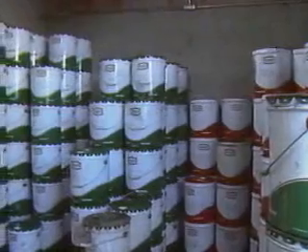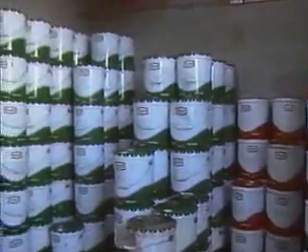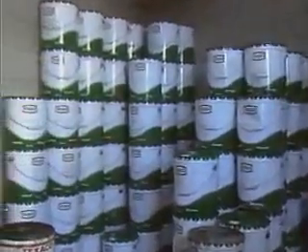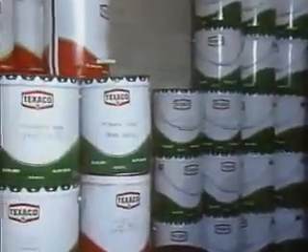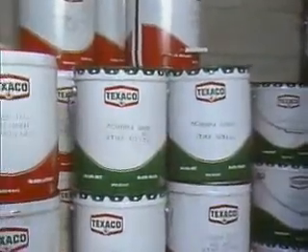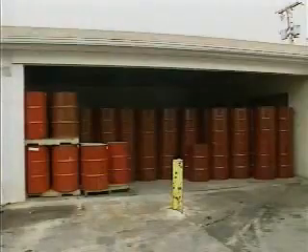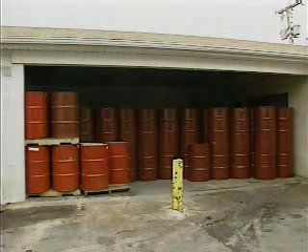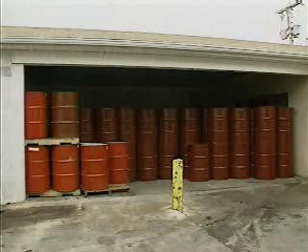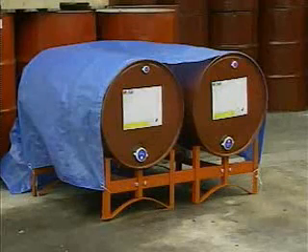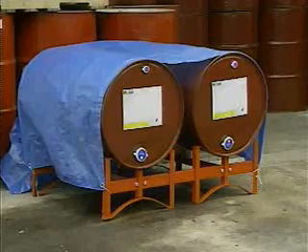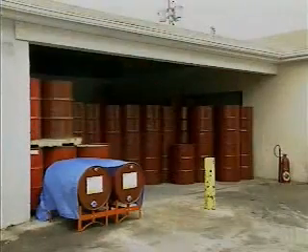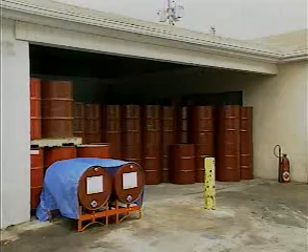After lubricants have been delivered, they're often stored in their containers for a long time before they're used. Depending on a facility's available space, the containers may be stored indoors or outdoors. Two major problems with outside storage are dirt and weather. So store lubricants in a location where there's a minimum of dust and dirt. Also, use a temporary covering like a tarp or a permanent covering like this three-sided shed to protect the containers from the weather.